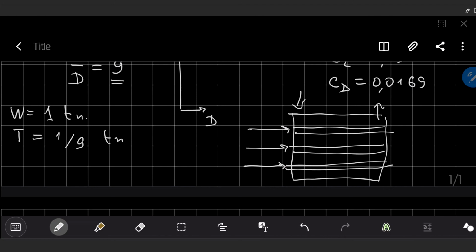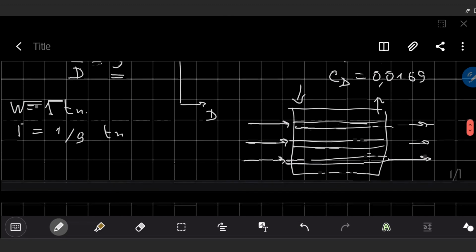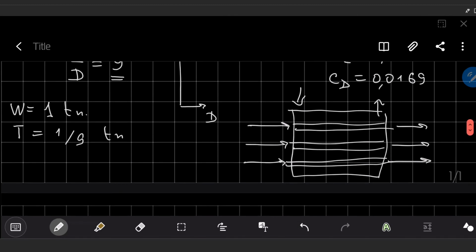It's basically a heat exchanger, and then you increase the efficiency of the engine. So if you do not install this, you lose performance of the engine. If you install it, you have some losses of the flow because you have an additional drag coefficient on this device. Definitely, you have drag because you have friction inside the intercooler, and because of friction, you lose some part of energy. So you have a drag.